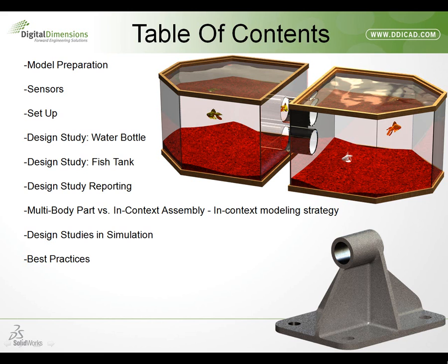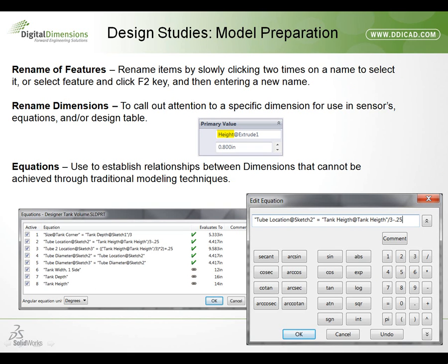Then we'll talk about some in-context modeling strategies, that is multi-body part design versus in-context assembly design. We'll talk about the pros and cons and what I recommend. Then I'll briefly show an example of design studies being used in simulation, and then we'll close out on best practices.